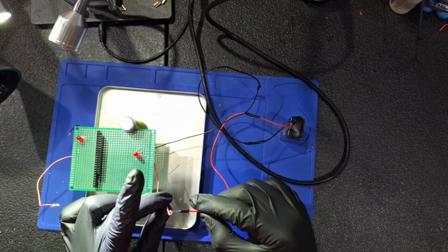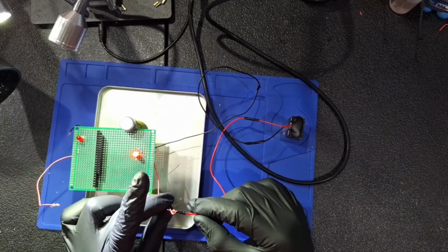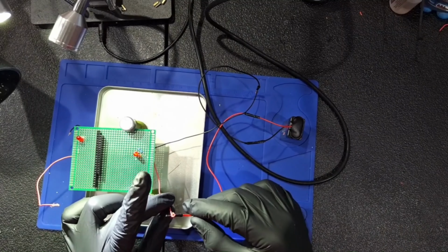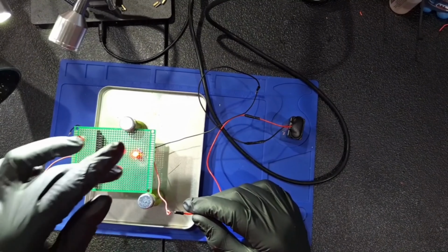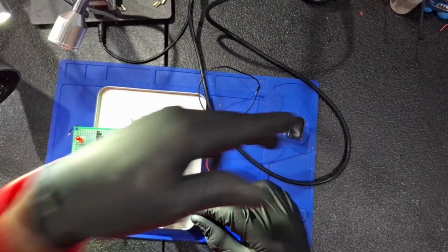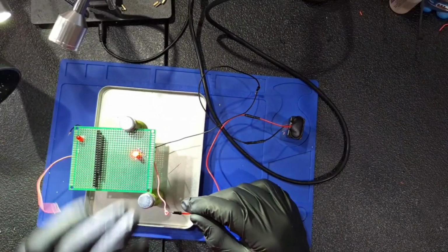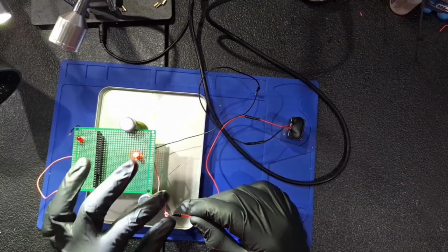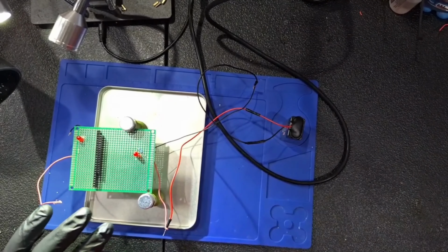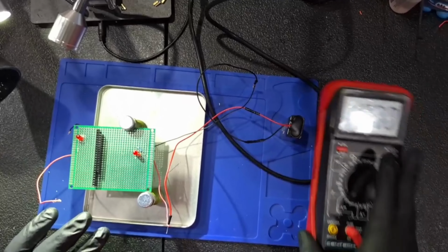Every time I touch the wires together, I get light, which means the current is flowing through the circuit. When I remove it, the circuit is open, or I break the circuit and I have no light. This is how I would actually go ahead and test current now, by breaking the circuit, removing the wires, and then connecting the multimeter in between. Yeah, it sounds easy enough, but it was not always this easy until I actually understood it.